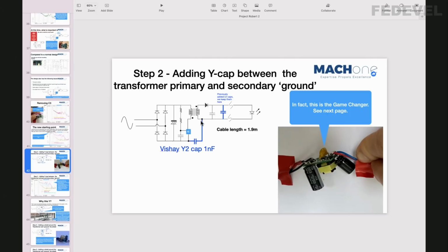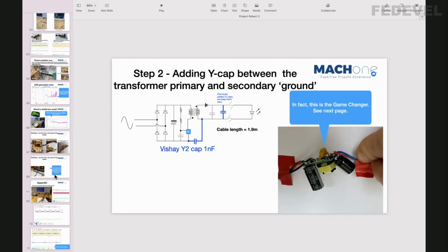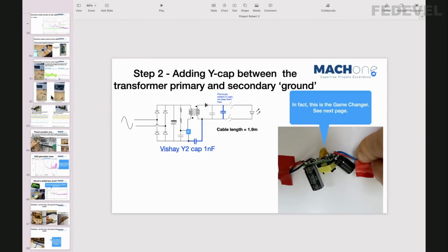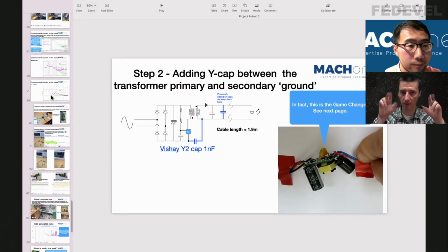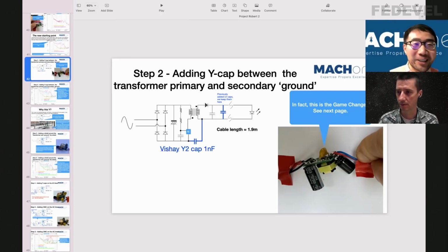In fact, I measured the common mode voltage, and you can see it's really bad. I have the measurement video if you want to see it. And it's pretty obvious that the common mode voltage is very high. And if we place the capacitor there, then we kind of make a short circuit for these high frequencies, and then the voltage will be the same on the cables. Yes, you are already jumping ahead. So basically, you understand everything. That's exactly what we're going to see.